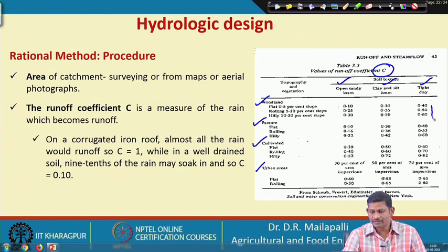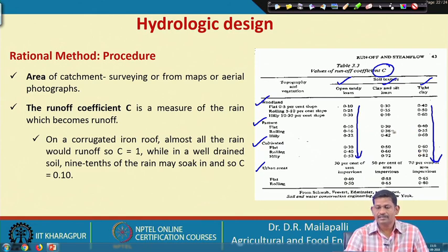If you see tight clay, it generally results in more runoff because of less infiltration. The values really increase when you go from woodland to urban areas. Similarly, in the case of sandy soil, the runoff coefficient increases, which means runoff is higher in urban areas. And also for soils, sand will have less runoff compared to silt and clay. You can clearly see that here.